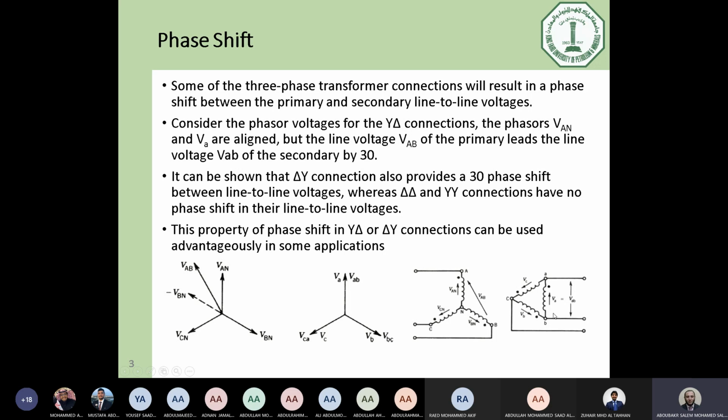Right. Regarding the delta connection, we agreed also last class that the EMF generated on the secondary side will be related to the phase value. So the value of V here will be transferred to V on the other side, but considering the turns ratio. If it is V here, the other side will be V over A, where A is the turns ratio of the transformer.